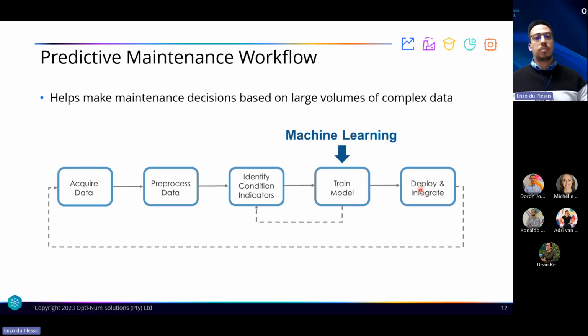Now, heading into the predictive maintenance workflow, what does this look like? The full predictive maintenance workflow is more than just algorithm development. The steps that I will go through entail obtaining data from sensors or synthesizing it by simulating system models. You pre-process the data and then extract the features to act as equipment health indicators. And these health indicators are used for condition monitoring and fault isolation.